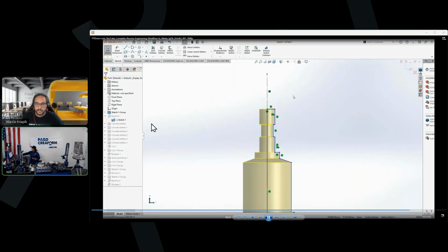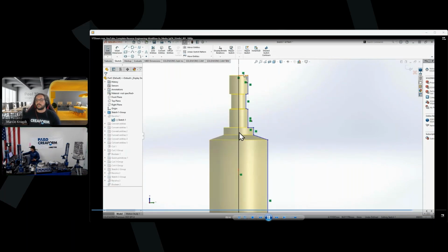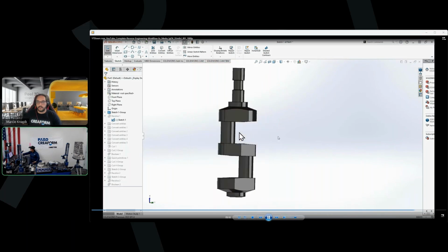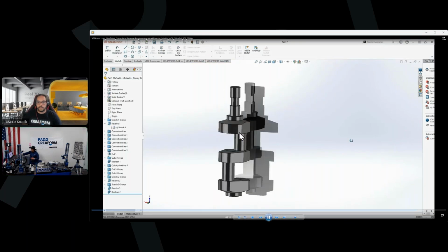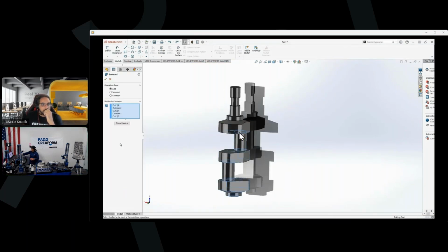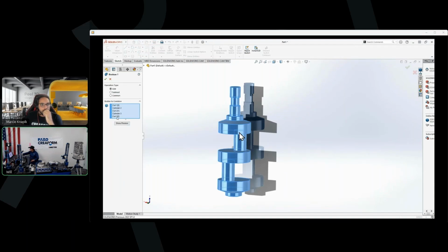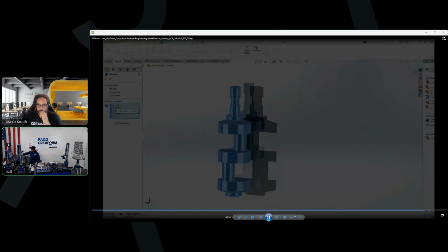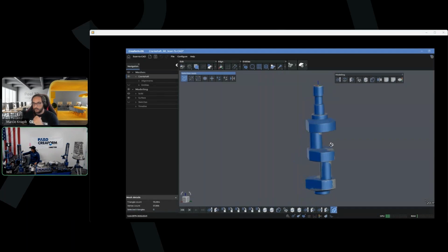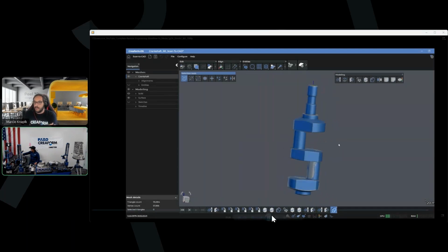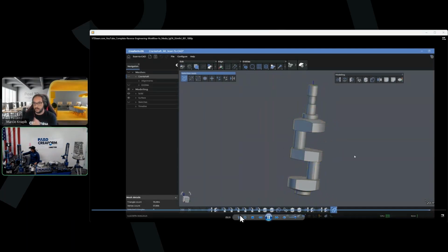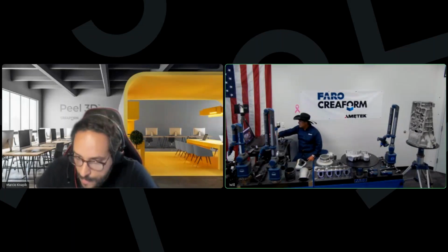The tree is editable. You can edit, finalize your CAD model in here, and you can even leap back and forth to Scan to CAD Pro if you want to fix something. So basically, that would be the biggest advantage of modeling inside here instead of modeling directly inside SolidWorks.